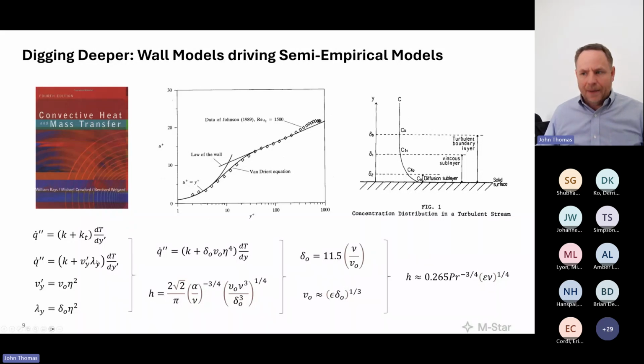So we know that if there is some sort of turbulent flow inside this boundary layer, we can relate the rate at which energy, momentum, species, etc., moves through this boundary layer to these fluctuations in the direction perpendicular to the wall and the distance they travel. We know from turbulence theory that we can relate these fluctuations to this friction velocity at the wall, as well as some dimensionless boundary layer thickness. This nu, that's just dimensionless thickness. That's just position within the boundary layer. So think of this as being position divided by delta. I don't have that here, but that's what it is.